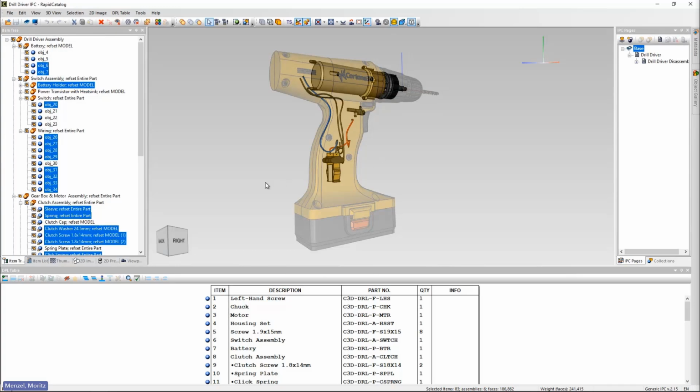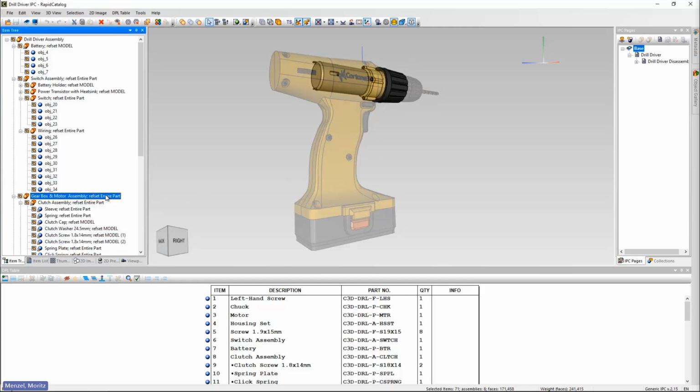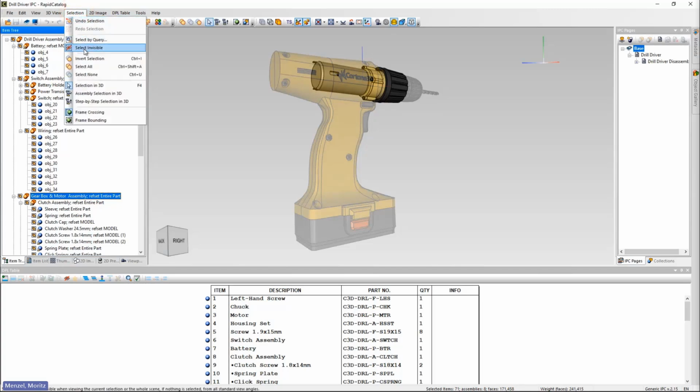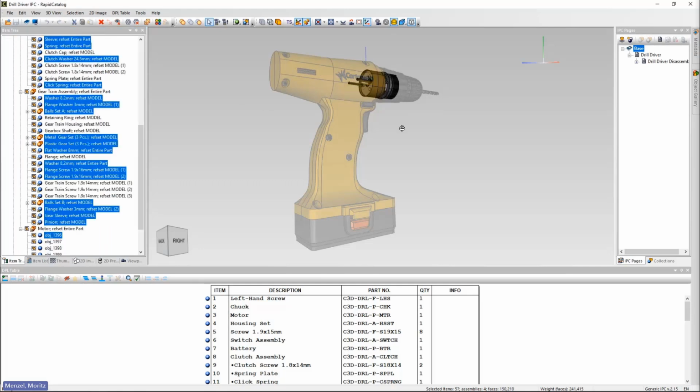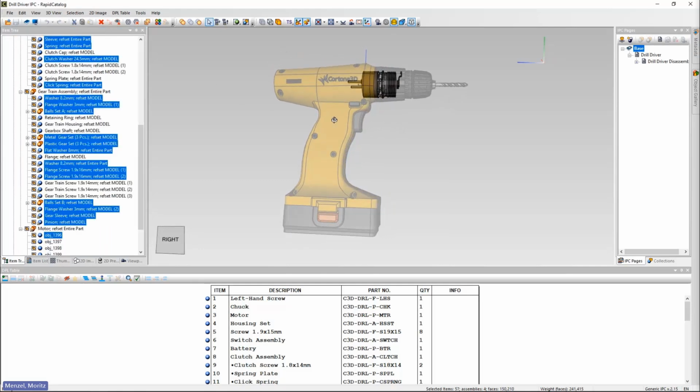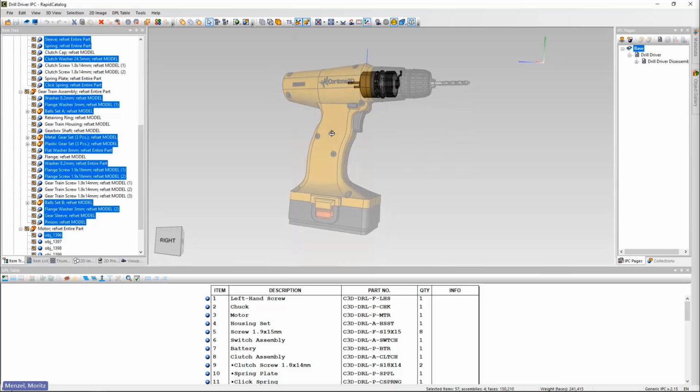To use the functionality, you just click the command, and then all items currently invisible will be selected for you. Then you can choose to remove them, or maybe reduce the representation only for these items. Doing this can drastically increase performance, and the new option saves you a lot of manual effort in trying to select internal components not relevant to your current authoring needs.